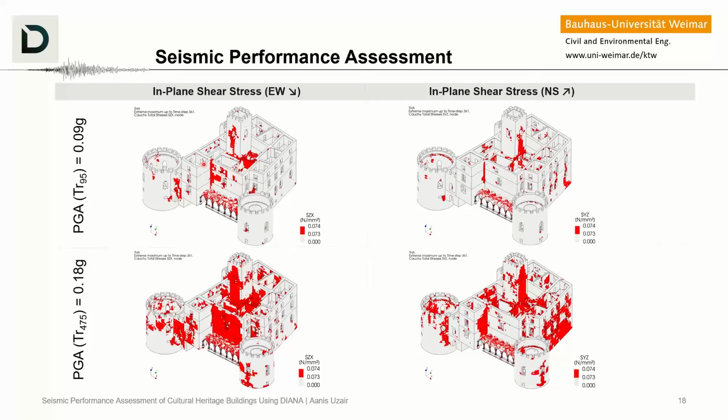But there is also stress concentration in the corners of the walls or near the openings, where you also expect them in the in-plane direction because of the irregularity that the opening brings to the distribution of forces in the facade.